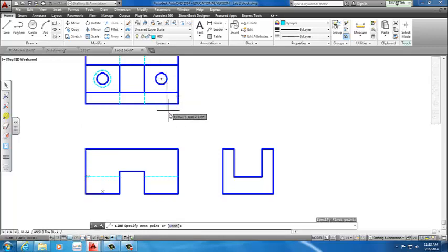We select that quadrant of the circle. We go all the way down my center line until we hit the bottom. At this point, that line becomes one piece. When I click on it, it's hidden. There we just create one line from this point to this point. To prove that to you, I can just select it, which I would recommend everybody do, and just move it over. If the entire piece moves all the way down, all the way to the hidden line, you're perfect. You're set to snap to that correctly.